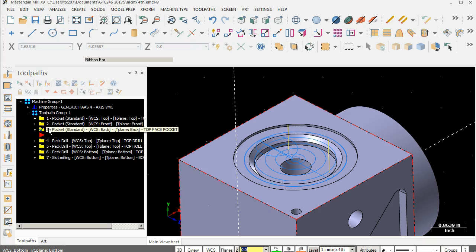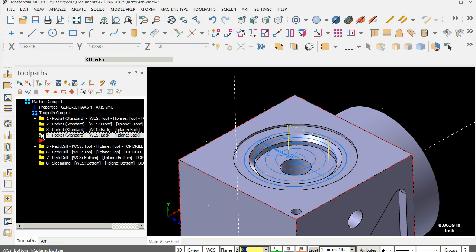What's that? So because you're gonna machine through that centerpiece to go to the deeper recess, would you let that first pass run all of that? Or would you do the first piece first and then cut just what's left on the outer lip?